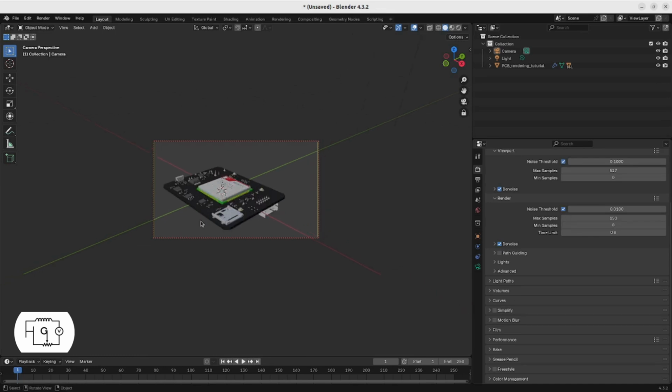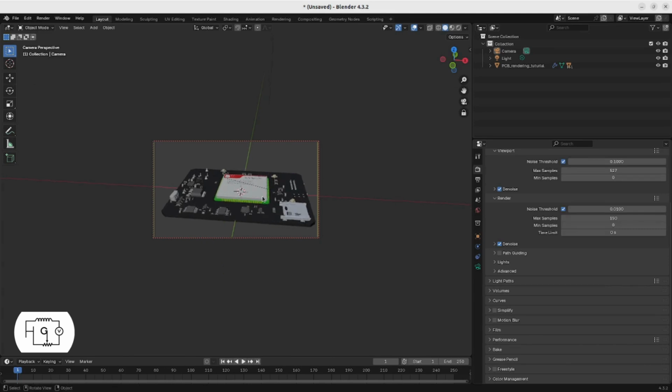One way to rotate the environment in Blender is by clicking down your scrolling button on your mouse and moving it around. So that is the way to rotate in Blender. You can see we've set this to a particular position we want.